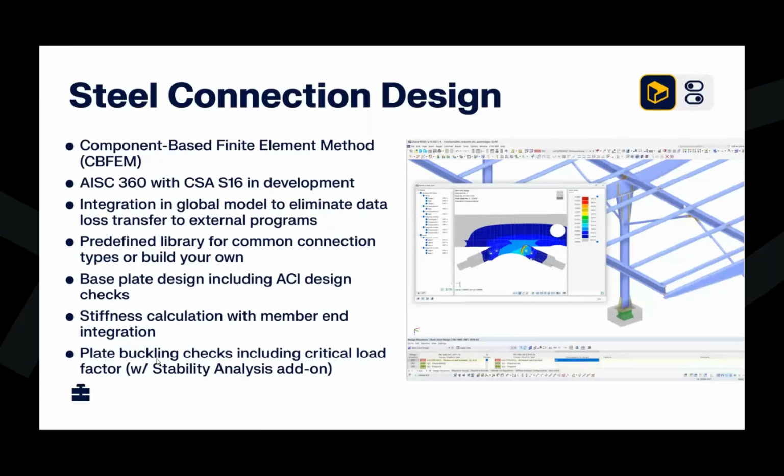So a couple more points to touch on here that set us apart from the other connection design programs is that you can carry out the full member design and the connection design in one file. So we no longer have to export out these member end forces. You can imagine that we have less data loss, or if we need to update the model, we're not having to re-export out those member end forces each time.